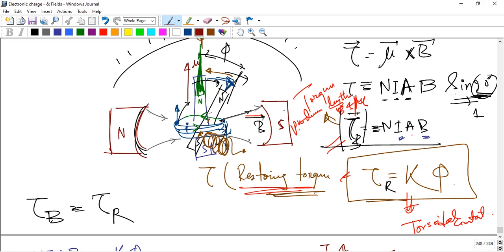Okay, so that's why there is some change here. Some external parts we added here, this galvanometer. After adding these parts, the galvanometer is treated sometimes as a voltmeter, sometimes as a current meter.